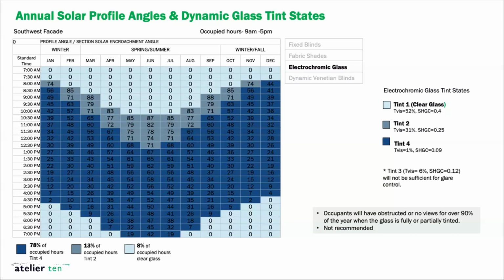Yeah, I think that was brought into discussion, but the bigger concern was the use of electrochromic glazing for the space in general because of the tint, even with the parametric tint. They felt it was a bit disruptive to the program, and they also wanted to ensure that even when we are providing shading, we're still keeping access to the view across the whole glazing. So they were more open to having Venetian blinds that are more consistent in terms of the views. It was in discussion, but ultimately they decided to forgo the idea of electrochromic glazing for this project.